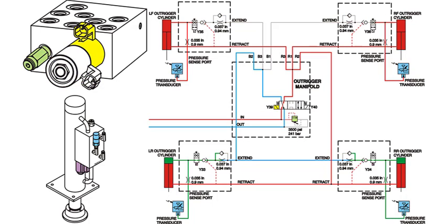As outrigger retract is operated, Y39 is energized, directing pump flow to the rod end of all 4 outrigger cylinders. The ECU provides outputs to energize Y33 and Y34 for 2,500 milliseconds. Pilot-to-open check valves meter the flow out of the barrel end of the cylinders, regulating the rate of speed that the chassis lowers. An orifice is located behind the pilot-to-open check valves to stabilize exhaust flow when retracting.